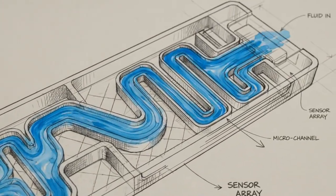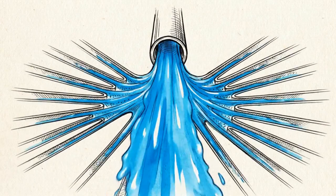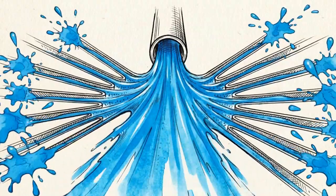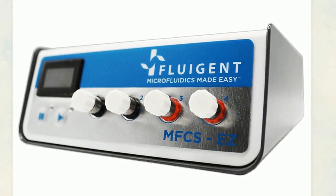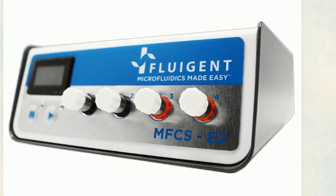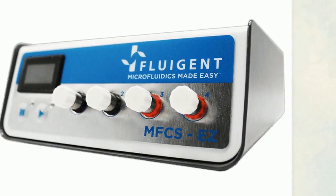This sequence of automated chemical lysis and magnetic separation exists entirely to protect the fragile transcriptomic signature from degradation and isolate it for quantification. The hardware must now take this microscopic volume of eluted RNA and route it cleanly across an 18-target reaction array, doing so within a desktop footprint. Active mechanical pumps introduce high failure rates and cross-contamination risks. Instead, the instrument utilizes external pressure and flow controllers to pneumatically drive the fluid through elastomeric microvalves on the cartridge.